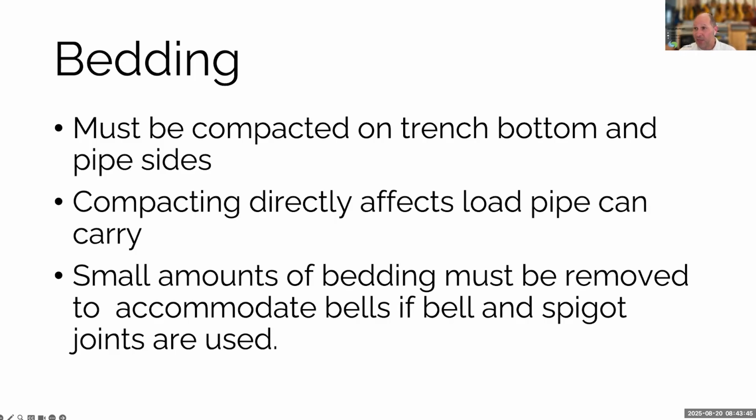At every joint, there has to be a little extra excavation to make room for that bell at the bottom, so that the pipe isn't canted up and sitting on that bell, because you don't want it to break.